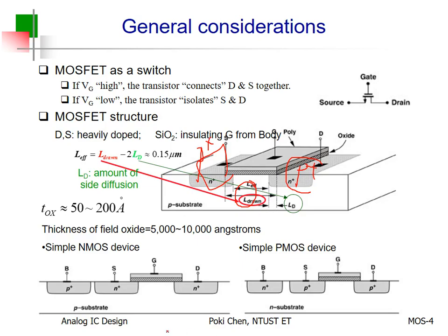And it means if you would like to fabricate NMOS, it is good enough on P substrate. But how about PMOS? It needs to be on N substrate. But from the very beginning, you have only one type of substrate. That is the so-called wafer. For your wafer, you need to think. To dope the wafer to be P type or N type, you have only one choice. So usually from the beginning, it is doped as P type. Then, how can you fabricate PMOS on P substrate?